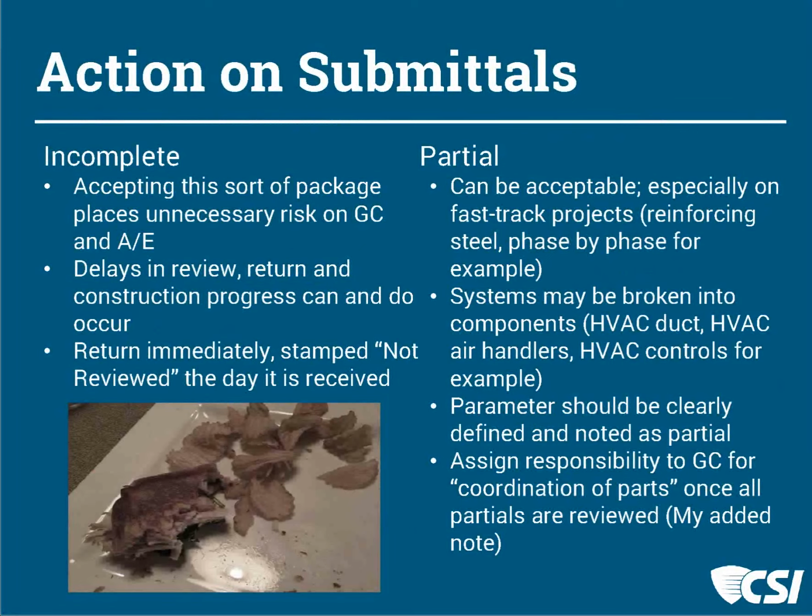So let me say that a different way. Often I will send the structural engineering drawings to the HVAC engineer, and I've told them this, and they've worked with me enough to know I'm going to do this, to ask the HVAC folks to take a look at elevations, heights of steel, dimensions of materials, to be sure we're not going to have any conflicts with ductwork crossing in certain spaces. Now, do I pay for that? Yes, I do as a fee, but I think it's important to have that kind of coordination.